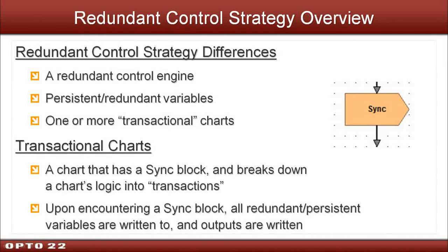Now, when a sync block is placed in a chart, thereby making it a transactional chart, it tells the controller not to do any writes in that chart, not to do any writes to any variables or any outputs until the next sync block is encountered.